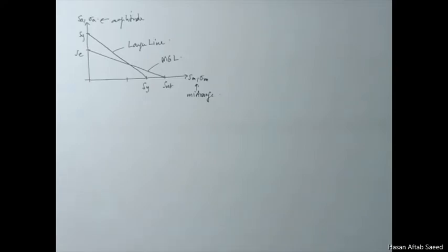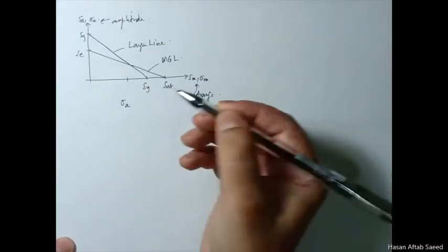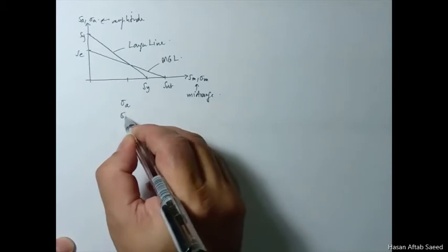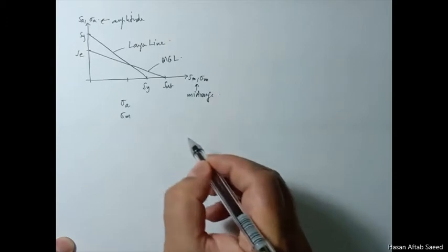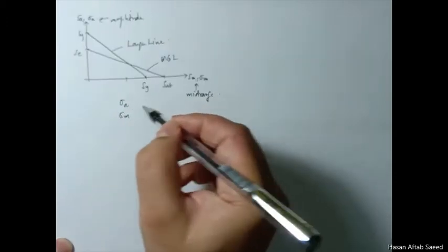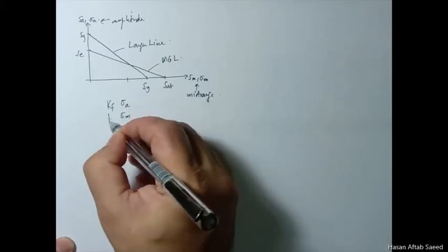In our last class, we had seen how to deal with fluctuating stresses. That is, where the mid-range stress, sigma m, does not have a value of 0. So in that case, you have an alternating component of stress, the amplitude component, and you have a non-zero mid-range component of stress. And both of these are achieved by using your fatigue stress concentration factors.